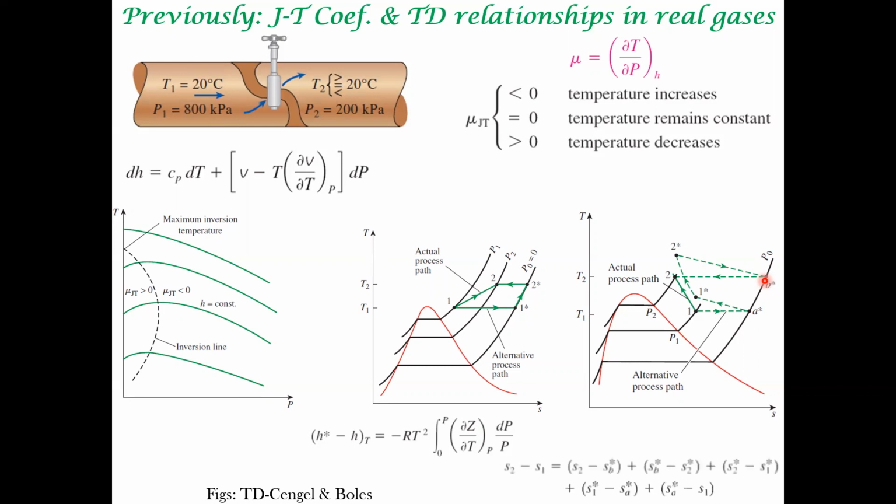In the end, we also had a chart which gives the entropy of a real gas as against the entropy of an ideal gas at the same temperature and pressure, and so on. All these things are tabulated in terms of charts: enthalpy charts, entropy charts, and so on.